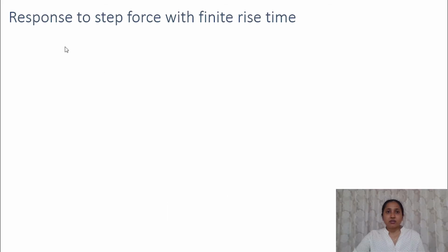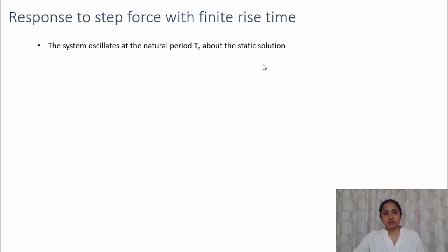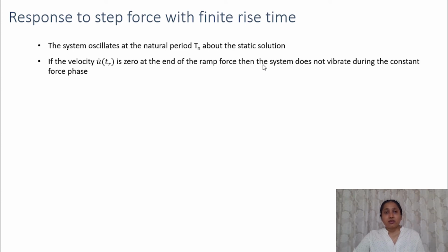Now let's conclude our observations regarding the response to step force with finite rise time. In this case, the system oscillates at the natural period Tn about the static response position. And if the velocity is 0 at the end of the ramp force, then the system does not vibrate during the constant force phase.